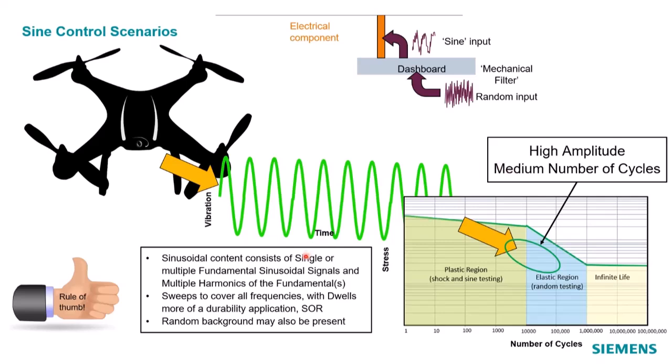This would typically involve modes, but we're going to focus on the sine sweep. You'll have some sinusoidal content in a sine sweep, and this can generate the fundamental sine frequency, but also the multiple harmonics of that, and if there are harmonics in the responses, you can get those, and that's going to be part of the signal that is measured.